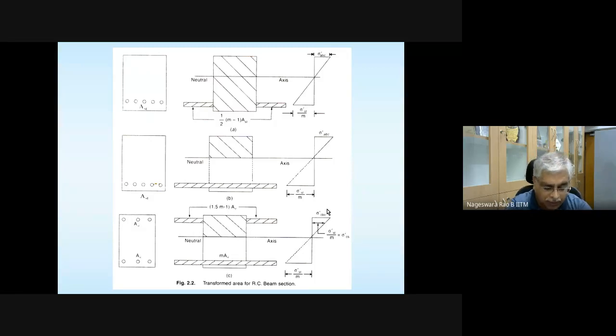Please note that reinforced concrete beam, let's say that section is actually shown here in this figure. This is a rectangular beam, a beam having rectangular cross section, and area of steel. Steel is provided in the bottom portion, and assuming this beam is undergoing sagging moment, bottom fibers are going to be in tension. So to take care of that tension, because concrete is weak in tension, we are providing some steel here. And those steel bars, whatever we provided, please note that this is a section.